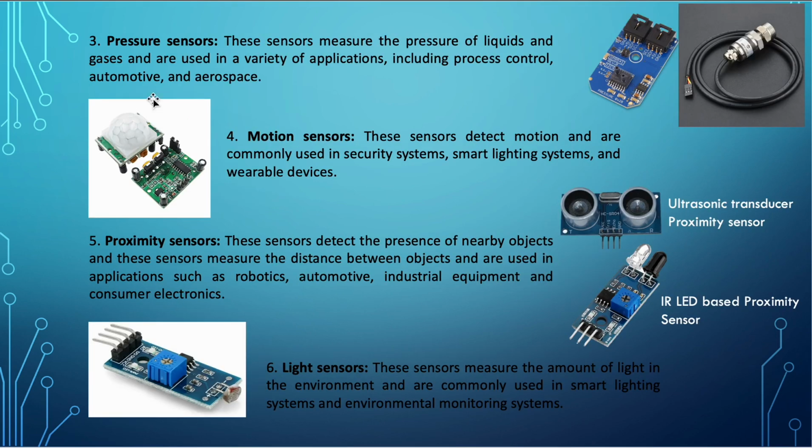For example, I will give one off the top of my head. An unusual example would be, again, pressure sensors. We talked about pressure sensors detecting the pressure inside pipes, right? It could be a liquid, it could be a gas, but when it's pumping in we can see. But we talked about the one next to it: if you know the size of the container, we can know how much liquid is filled in by checking the pressure at the bottom of the vessel, right? So different applications. It's not a pipe and it's not being pumped, but that is a different application.